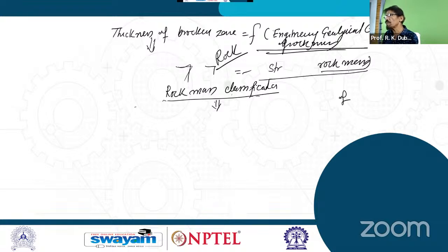It is an attempt, and still we are trying, to translate the information related to ground or geological formation into some numerical values, so that engineers or planners or other persons can utilize the values for calculation of load, for proper design and planning, and construction of engineering structures like tunnels, caverns, underground spaces, etc. Rock mass classification is an empirical approach to quantify the ground in terms of some values.